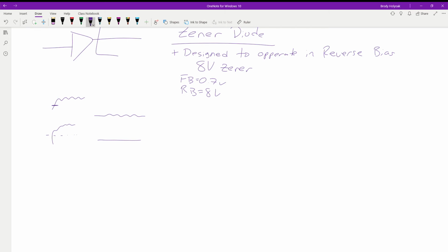And that's really important, because if you have circuits that are designed for a specific voltage, as you guys have noticed, when things start deviating, your values farther down the line end up not coming out close enough. So if you have something that varies by 5% in your power, your output values are going to vary by at least 5%, probably more, because it's going to affect things farther on down the line.